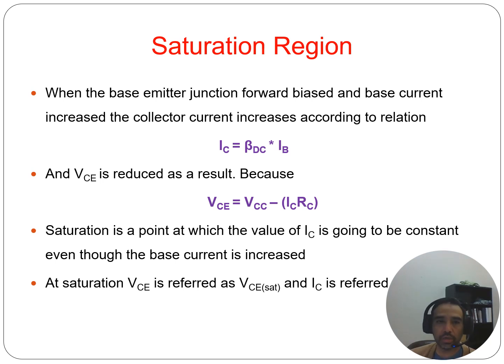You can also calculate it if you didn't know it. If you had a component, you pull it out of a drawer, you don't have the spec sheet for it, you don't know what the beta is, but you need to know what the beta is for design. You can do a couple of circuits, do some measurements, and calculate the beta so you can get an idea of what it is. There's some standard values for betas. So if you see it's close to a certain number, you can pretty much guess what it is. And actually, it might be good to calculate the exact beta.